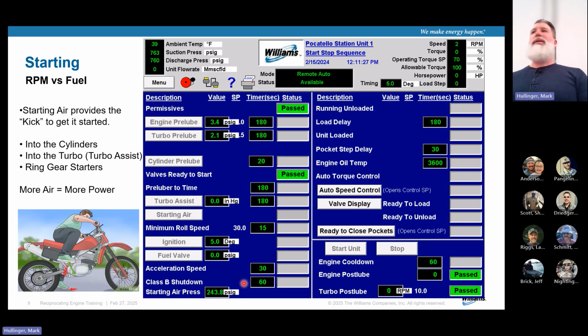So a lot of times fuel is what you're going to look at, right? Governor, combustion problems. So fuel might be some of your go-to, but you guys got stories galore of things that you found that would be odd that you wouldn't think about. And then when you dial it back, it's going to be one of those three: ignition, fuel, air. Okay.